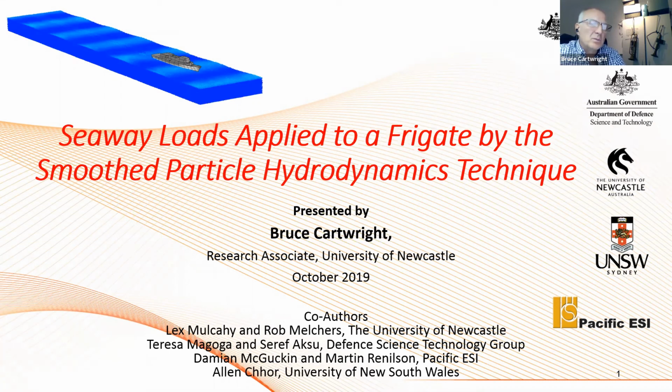And yes, the whole reason to develop this moving floor technique was partly to overcome that damping. We couldn't actually get waves to maintain any useful amplitude if we just started at one end and had them propagate down a tank like you would in a wave tank. The moving floor overcame that because we only had the depth through which to lose energy, compared to along the whole length of the tank.